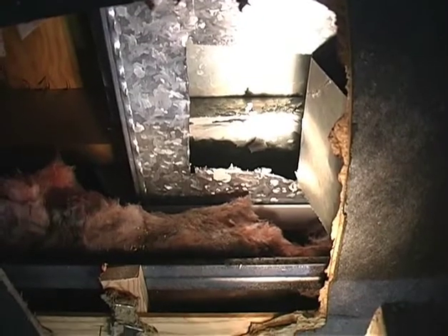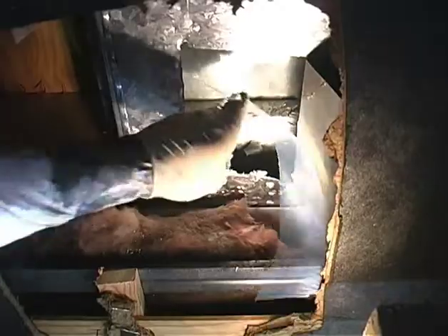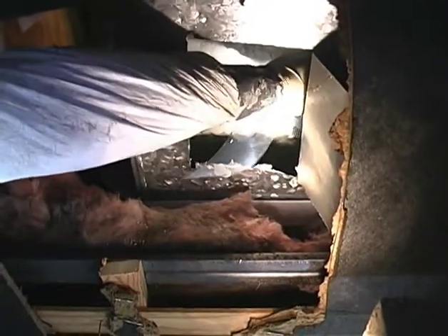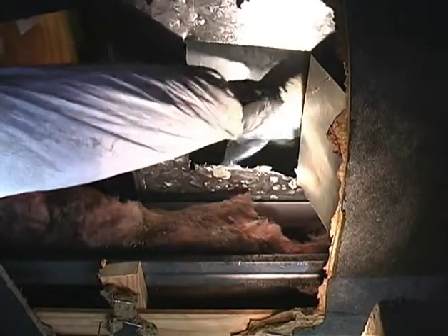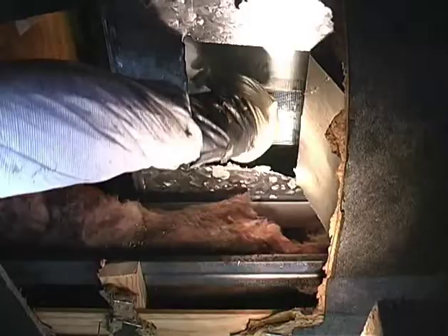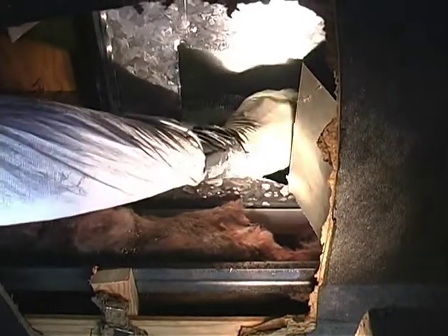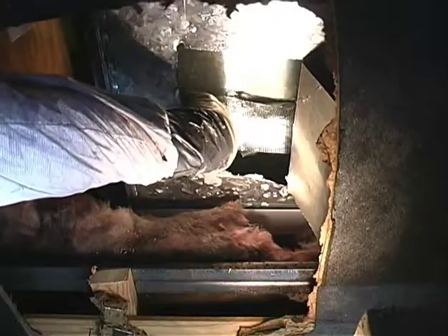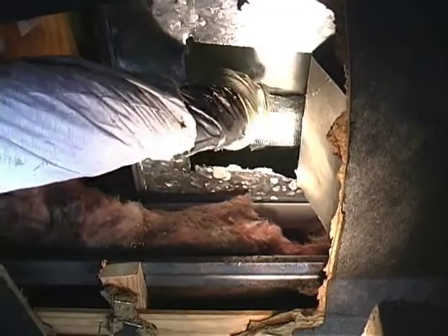When the ducts heat up, the two pieces of metal move at a different rate, and this mesh tape will assure that the seal stays when the two ducts start to move, the two different places where it comes together there. So he's placing the tape up into the mastic, and he's embedding the tape in the wet mastic that he has between the trunk line and the branch duct.